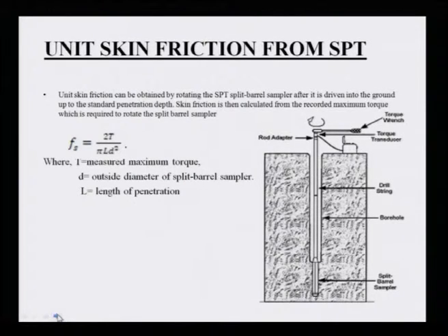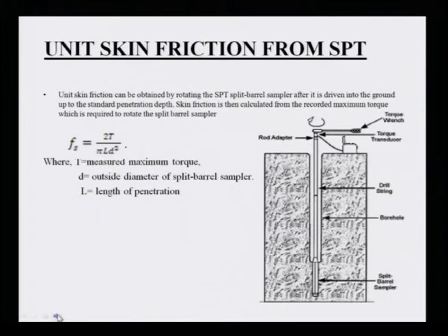Now, another important part I have not said: can I measure unit skin friction from SPT? Yes. It is the latest development, meaning unit friction can be obtained by rotating the SPT split barrel sampler, split spoon sampler here.